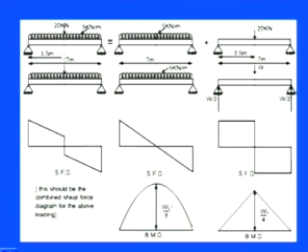With that, our main intention is to combine those loadings, because here we have the UDL as well as the point load. With the combination of those, as I told you, the maximum bending moment comes from WL by 4 or WL square by 8. So we simply combine those loads, the UDL plus the point load, and then the reaction forces come out.